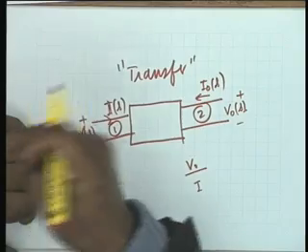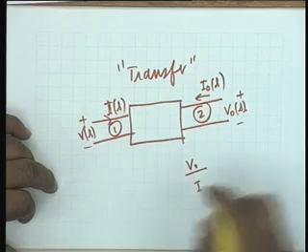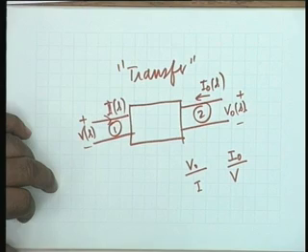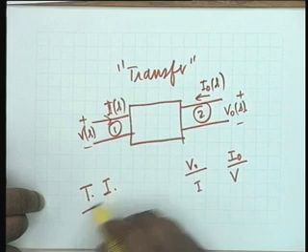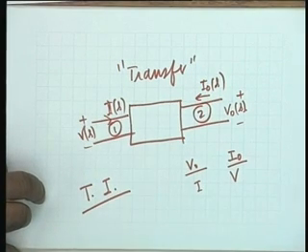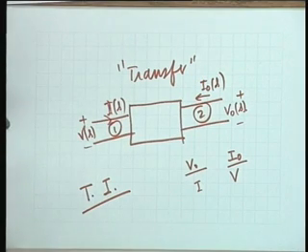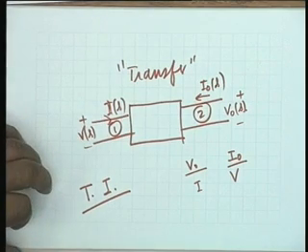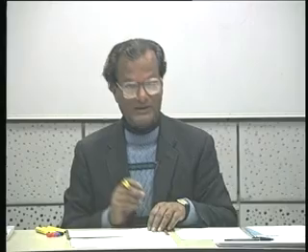This is why we call the previous one driving point, to distinguish between transfer impedance and driving point impedance. Similarly, if it is, let us say, I0 divided by V, then it is a transfer admittance, and in this case we define what is known as transfer immittance. It can be either an impedance or an admittance, to distinguish it from driving point immittance. These terms are not important in general systems, but in circuits they are very important. As you shall see, the driving point synthesis problem is much easier than the transfer function synthesis problem, and this is where we close.